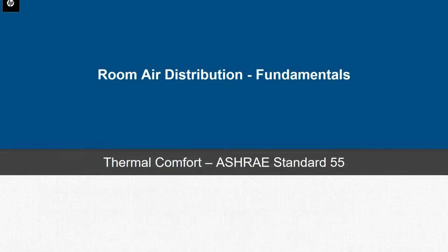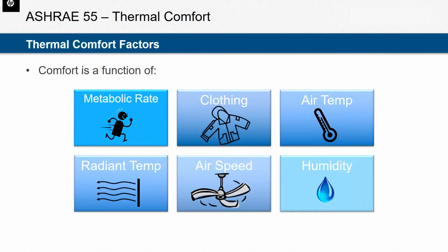Now we'll look at some important ASHRAE standards that guide us towards using our diffusers in a way that promotes a comfortable, well-ventilated environment. The first we'll look at is ASHRAE Standard 55. This is designing for thermal comfort, and it goes into all of the details you would need to know that correlate between air movement, temperature, and human physiology. How do we as occupants relate to the environment around us, and what results in a thermally comfortable environment?